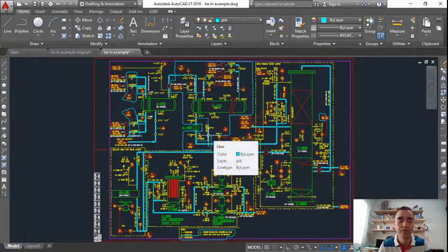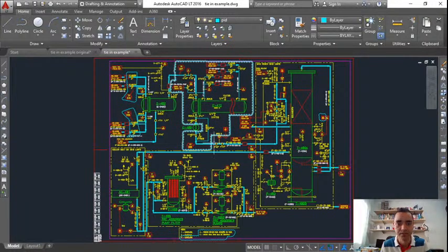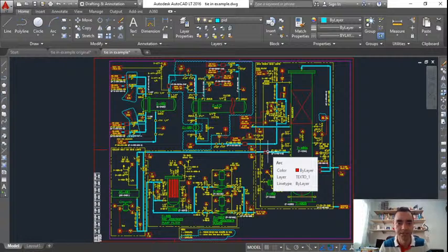And of course, when we are doing that, this is an activity that can produce sparks, and it produces heat. And to avoid any kind of risks, we must guarantee that we don't have any kind of flammable here. If we are talking about corrosive, or if we are talking about dangerous streams, it is the same. We need to guarantee that it is empty.